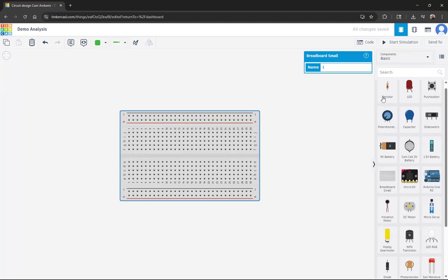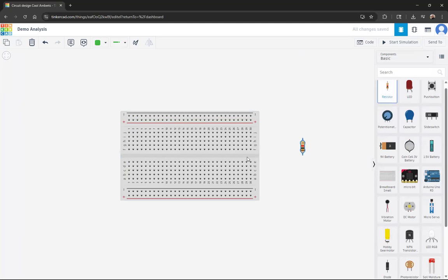So when, for instance, I go to drop a resistor in, I can click resistor, and I want to make sure I cross two holes, right? These two, even though they're in the same column here, are separated by this center line. So it's important to remember this quick intro on how the breadboard operates. The five holes are linked together, split by the center. So there's two groups of five that are linked, and then the horizontal rows here are all linked together. So we can put, say, power on one side or common on the other side and link everything together.